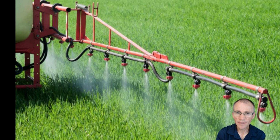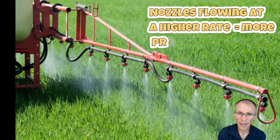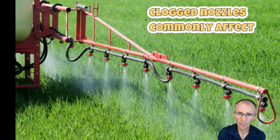Now, in my mind, because I've done this since 1999, some of these things seem pretty simple to me, but I can tell you when I first started, they really didn't. When I look at number 1, as we talked about our nozzle flow rate, the flow coming out of the nozzles has a big impact on calibration. So if those nozzles are flowing at a higher rate, we're putting out more of the product if we're moving the same speed. At the end of the day, one of the biggest problems is going to be clogging in the nozzles, like pesticide buildup.